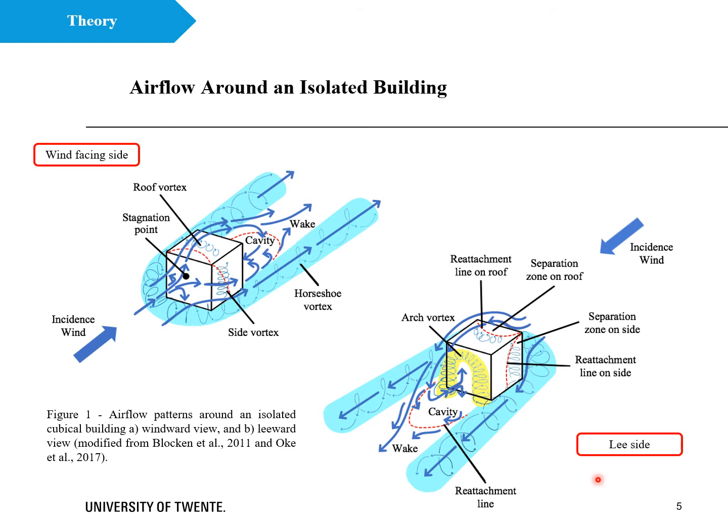If you look at the flow field, you can see the complex recirculation zones in front of the building, on top, around the lateral sides, and also behind the structure in the downstream cavity region. The length and size of these recirculation zones depend on the building dimension, geometry, orientation, and so on. These locally perturbed wind flows alter the sediment transport pathways.